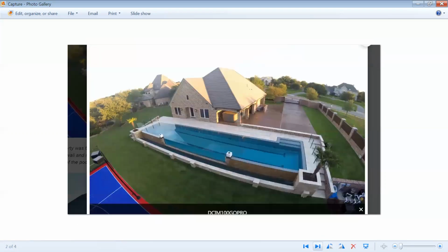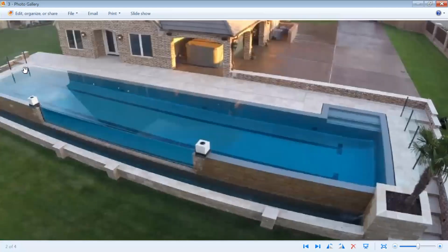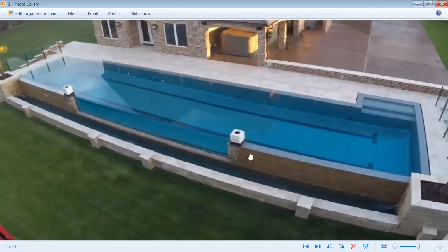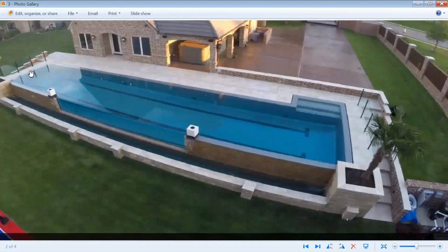So again, any type of edge that you choose, you need to consider what the edge needs. For example, this is glass and it needed to be perfectly level because the water ran around all 360 degrees of this design. And you also need to consider, not going to discuss it here, but waterproofing, making sure you have a waterproof vessel, because if you don't, you cannot possibly flood test it. So again, some very crucial details about negative edge materials.